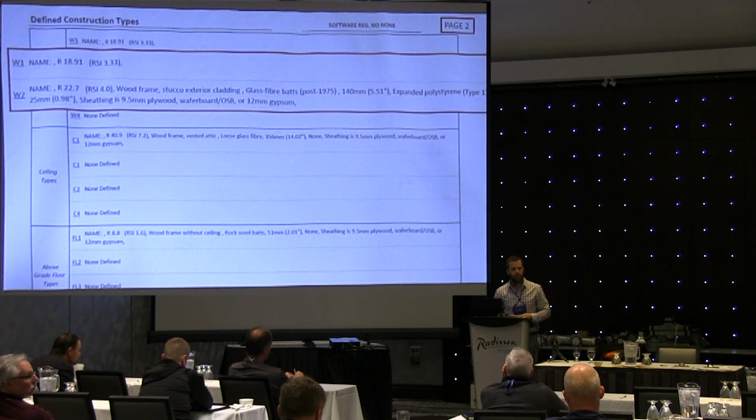Yeah, because you said that the effect of thermal, if you have 2 different materials, it's going to change. So on the front of my house, I have R20, but I know I can save a bit on the side by doing siding. I got R18, for example. When I define my room that has walls facing the front, I choose wall type 1 because I know wall type 1 is R20. But when I'm on the room facing the side, I choose wall type 2 because I know wall type 2 is R18. If we have time at the end, which we may, I can even show you the software a little bit, and you can see how that's done.